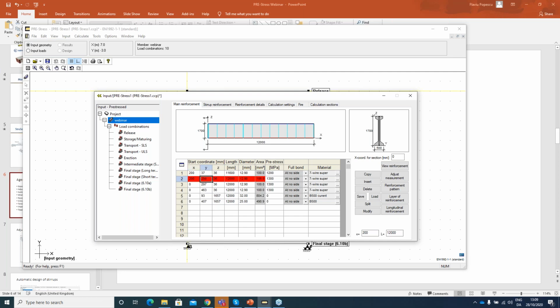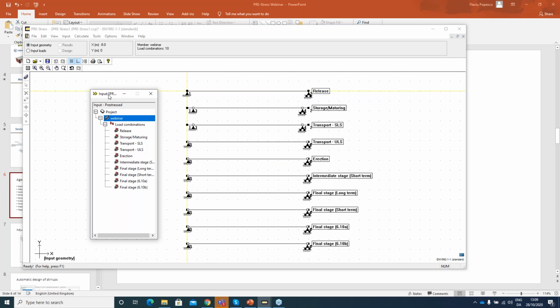so that the tendon actually starts from within the beam with the amount that you type in here in the x section. So you would actually have 200 millimeters of non-adherence in the ends. This is how you can simulate this non-adherence in the program. It's something that people have been asking about, how you could do this. It's very easy. It's very common and very useful to use.